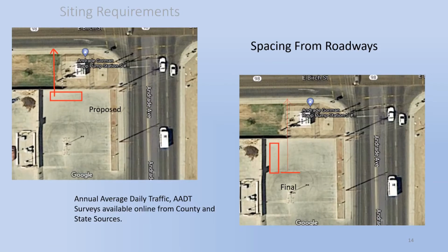However, when we evaluated the annual average daily traffic numbers for Highway 98, it was apparent that the original layout would not work. So we opted to use the 40-foot length of our shelter to our advantage and rotated it 90 degrees, allowing us to place our probes for gas and BAM further away on the south side of the shelter. As an aside, since it had been built to our specs, we had to make sure that the electrical panel would be adjacent to available power, and this then determined which way our door would face.